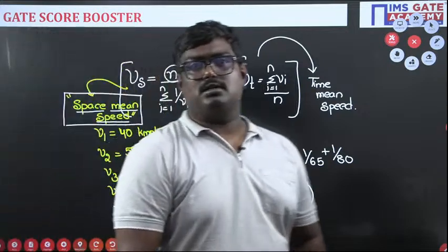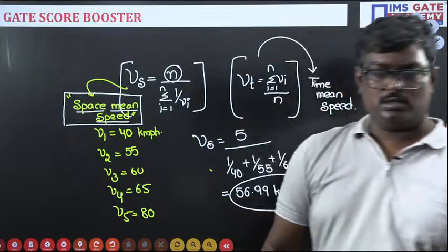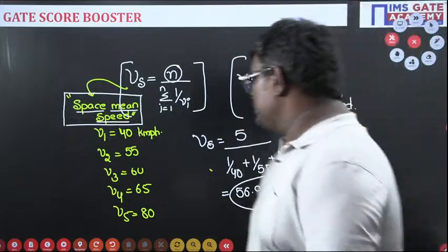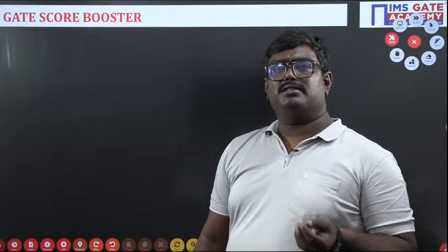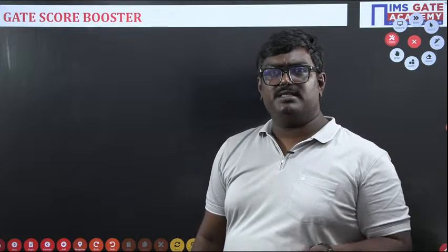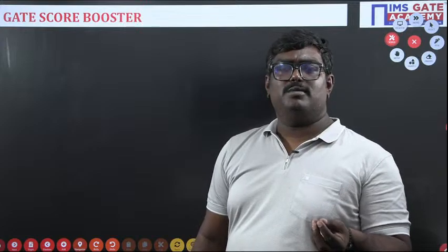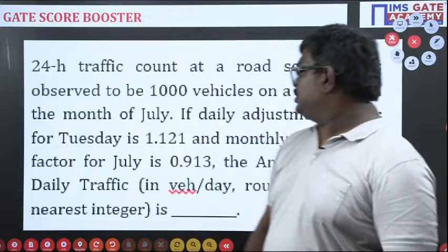Clear, sir? Let us go into the next problem. So the key points in this problem, students, are that the space mean speed is the harmonic mean speed and the time mean speed is the average mean speed. Now please solve this problem, students.